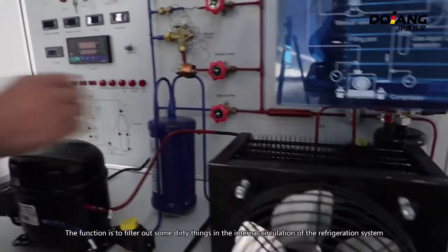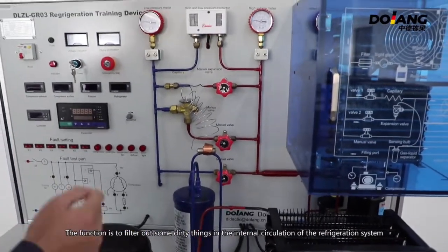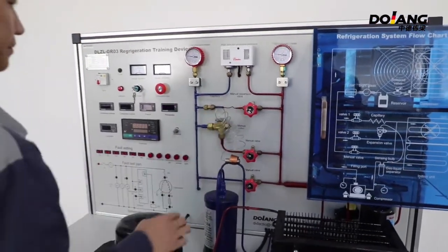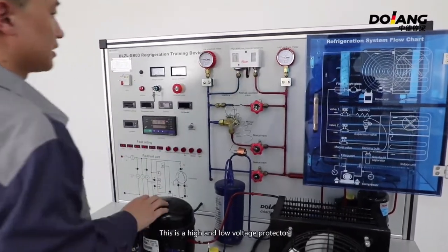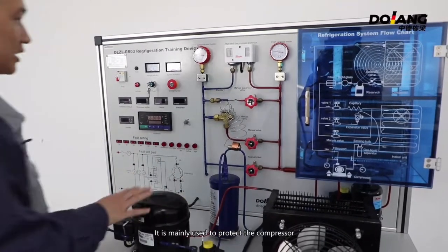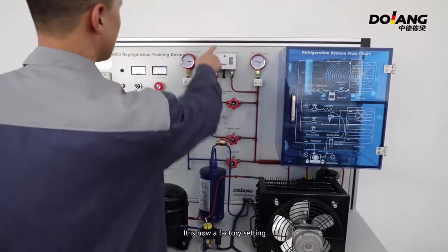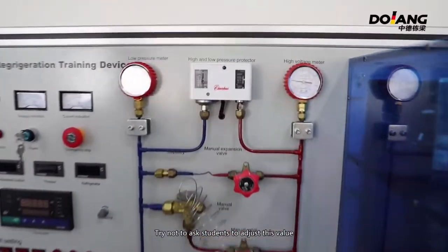This is a filter. The function is to filter out dirt in the internal circulation of the refrigeration system and prevent the throttling device from clogging. This is a high-pressure meter. This is a high and low voltage protector. It's mainly used to protect the compressor. You can set a value on it. It's now a factory setting. Try not to ask students to adjust this value.